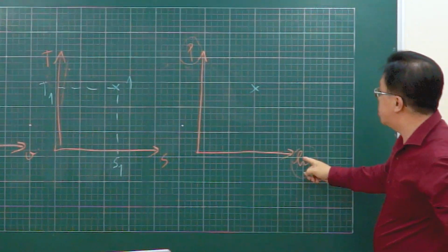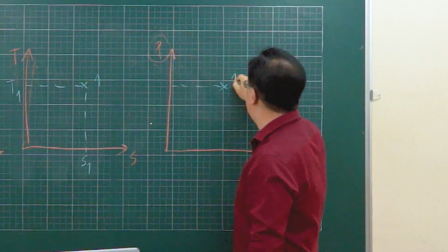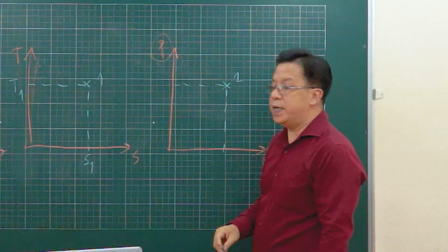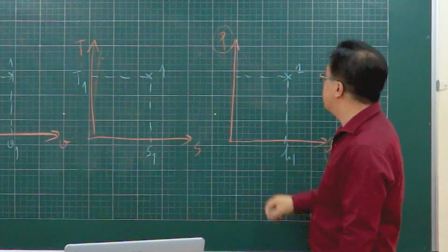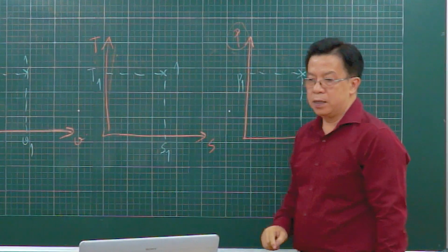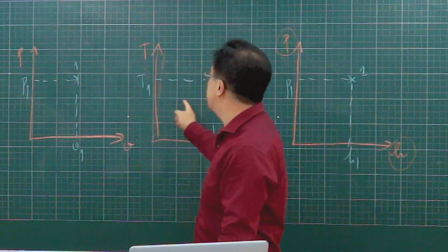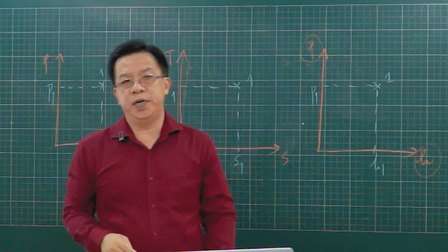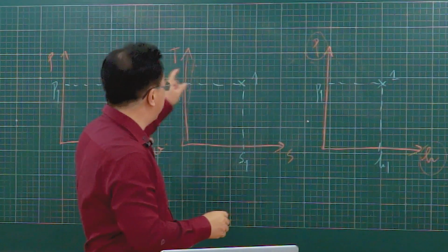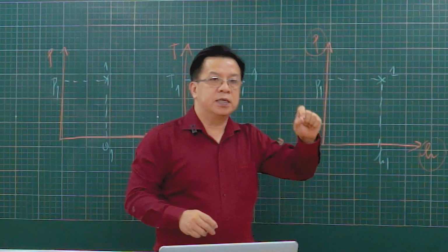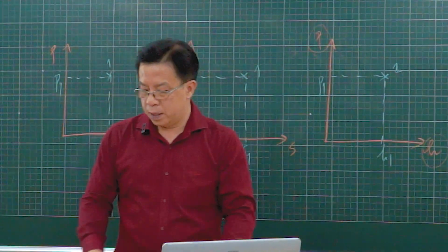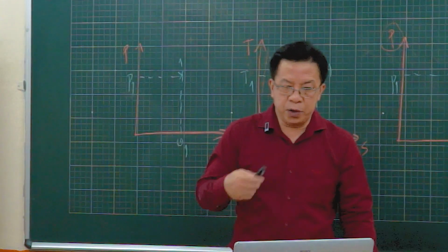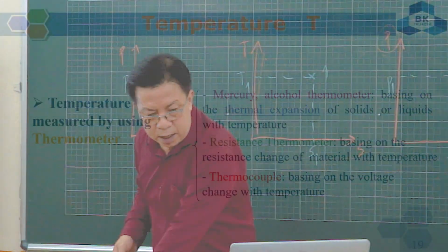Or in the PH diagram, we got point 1 as the state 1 determined by two independent properties, that is H1 and P1. Okay, so you see we got different kinds of diagrams, and each diagram is constructed by two independent properties. So it means each point in this diagram gives us a state of a substance. All right. Now we go into each property.